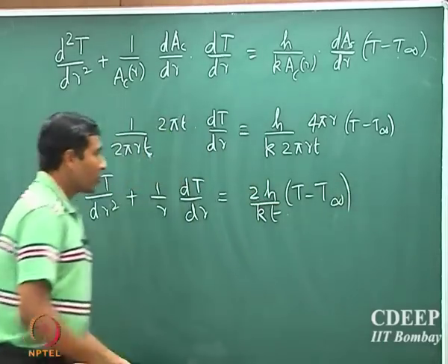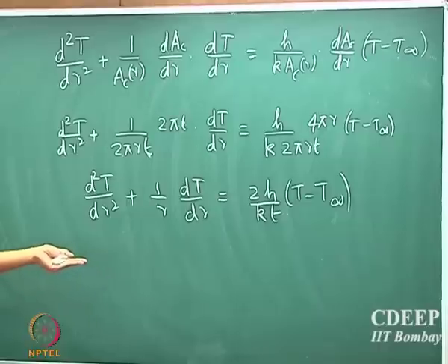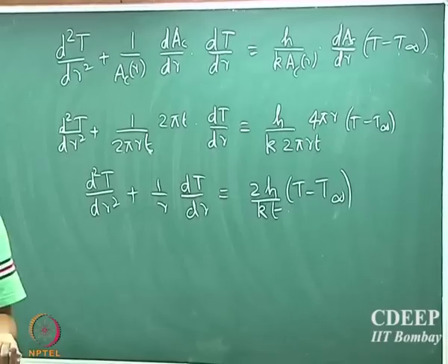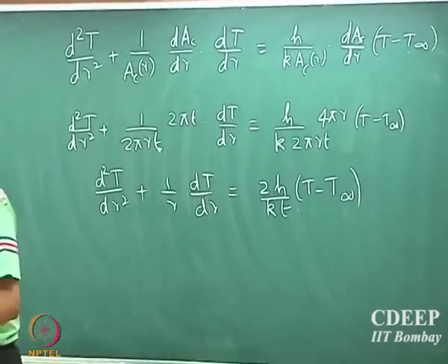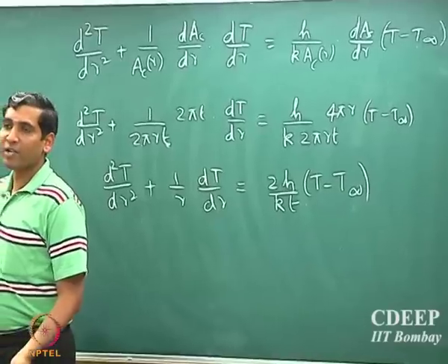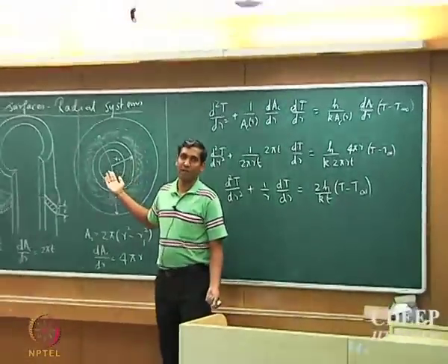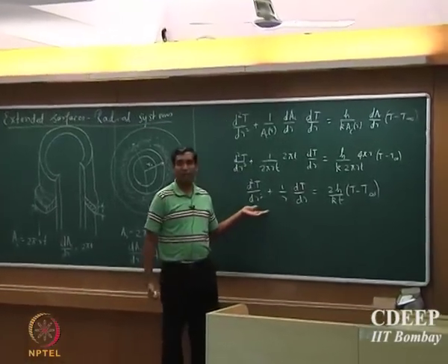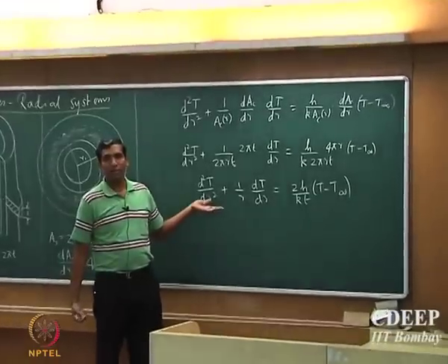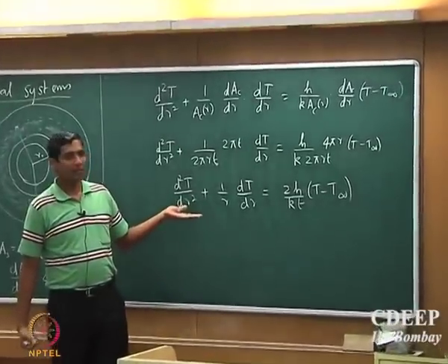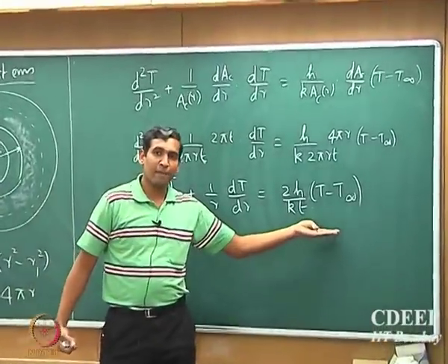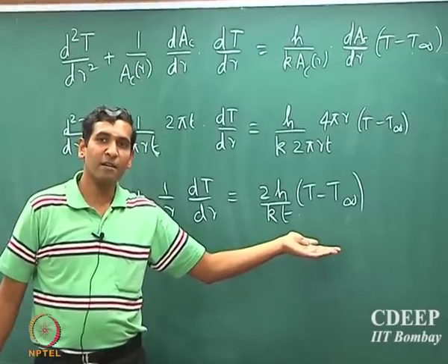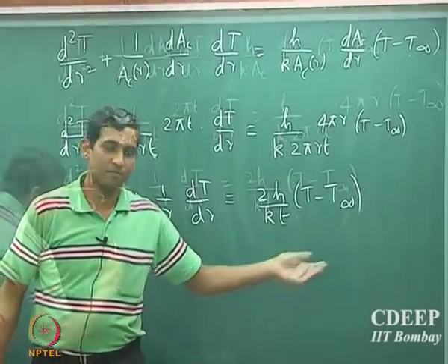This model equation completely describes the heat transport via thermal diffusion in the fin and the convection from the top and the bottom surfaces. The first term, the left hand side term, captures the thermal diffusion of heat in the fin, and the right hand side captures the heat transport via convection from the top and the bottom of the fin.